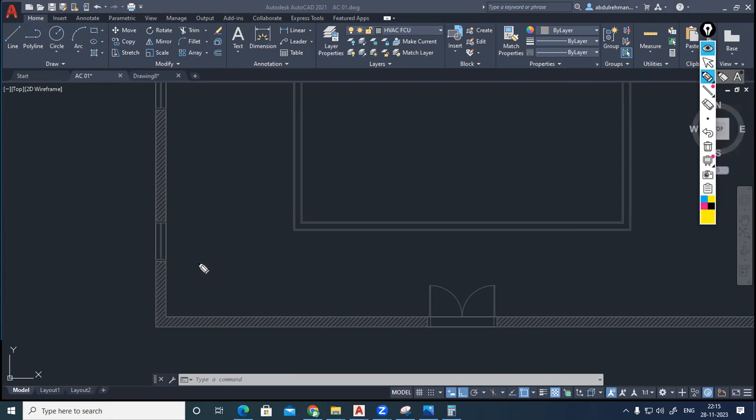For example, this is my fan coil unit. The fan coil unit, in 90% of cases, will be taking a return from the backside only. So if you're having doubt in machine, don't worry, we will study that. Okay, this drafting class, as I told, is not a design class. But before starting the HVAC project, the drafting has to be thorough. So that's why most of the machines will be taking return from the backside only.